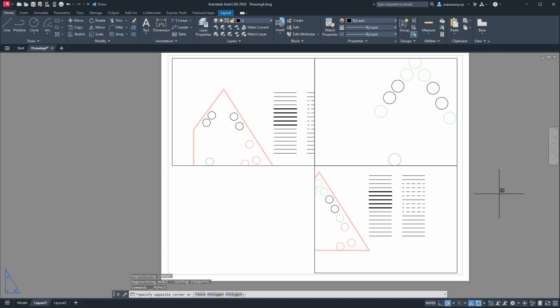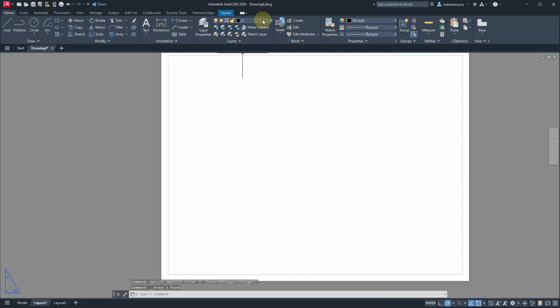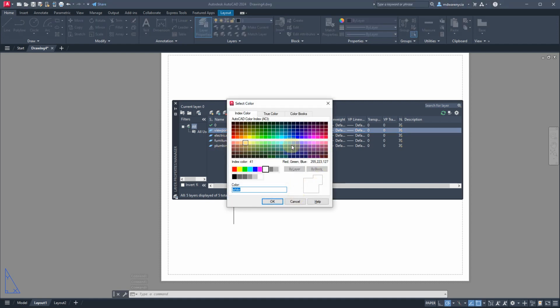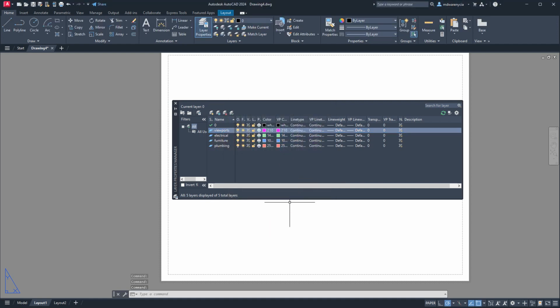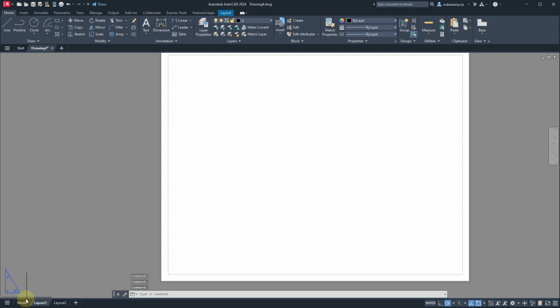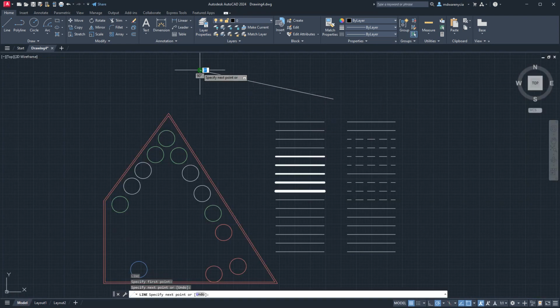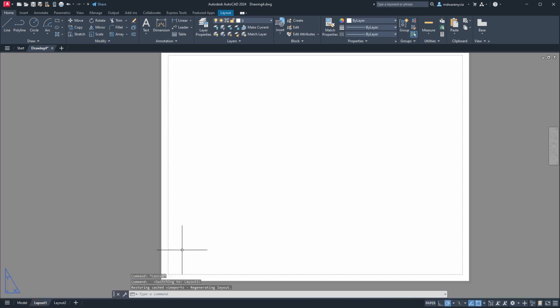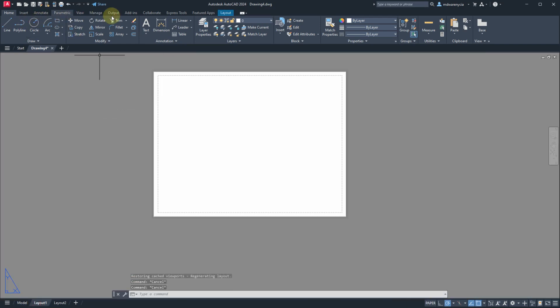Another thing you can do with viewports, let me actually create a viewport layer and we'll get a bit deeper into this. So viewports, this is something that I like doing, and it's just a way that I work: anytime I have something that I don't want to print, I give it the ugliest fuchsia color I can. And the reason why is because if I'm ever working through something, if I have notes or some weird test thing I drew, and then I move this over to this viewport layer here, which we'll use in a second, anytime I see that fuchsia, I know I need to hide that. And one thing you can do with viewports is viewport.